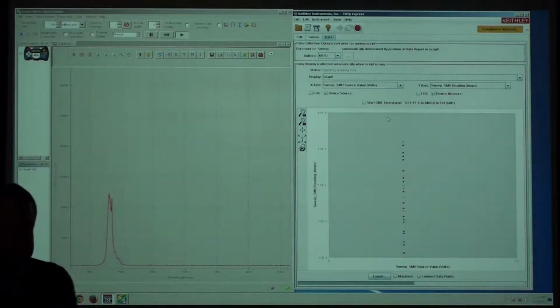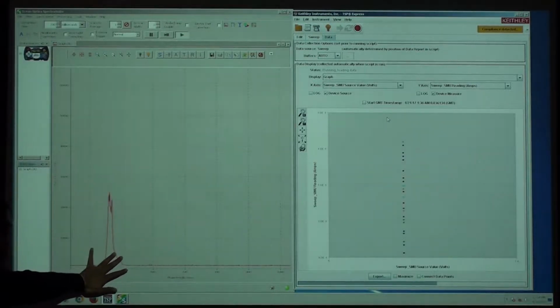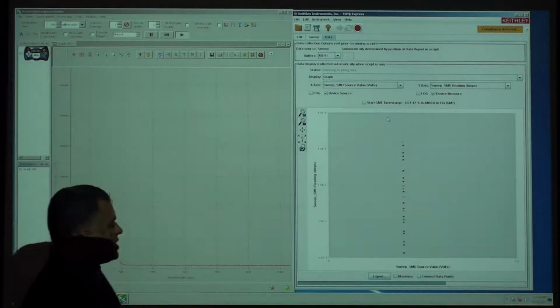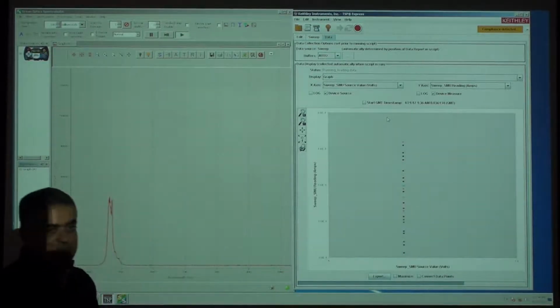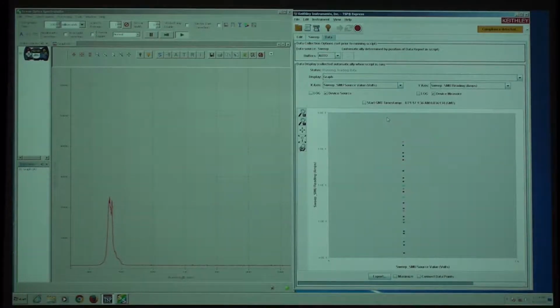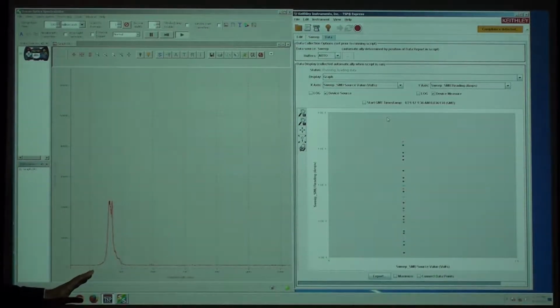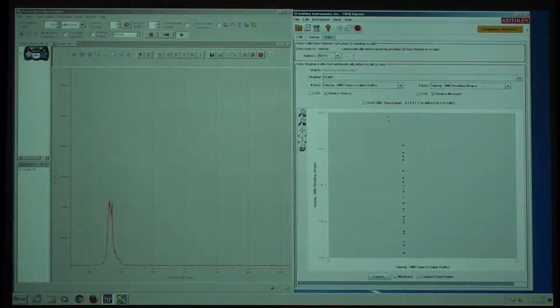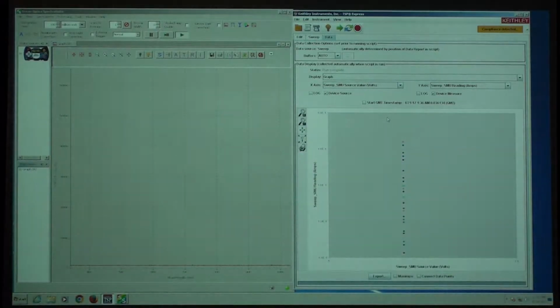Could it also be spontaneous emission? This is currently all spontaneous emission. At this point they're injecting some current, but you are not above the threshold of the laser yet. We'll cover that part in the later courses, but this is spontaneous. There's no stimulated emission yet. Only when you exceed a certain injection current will it go into stimulated.